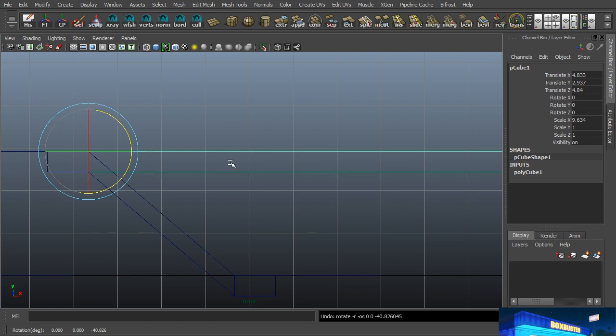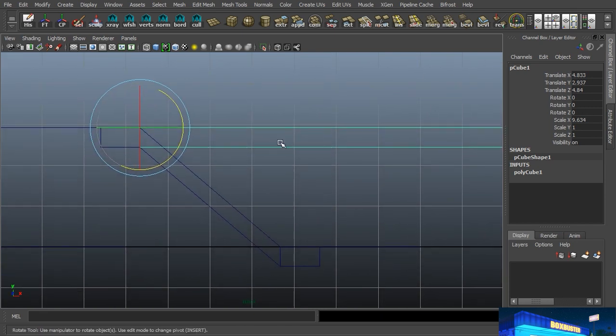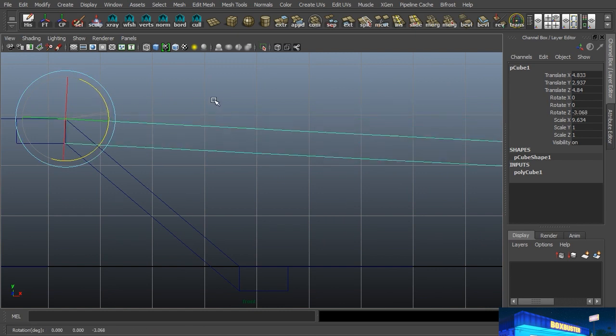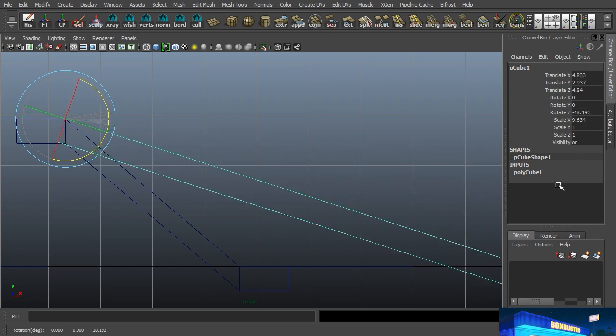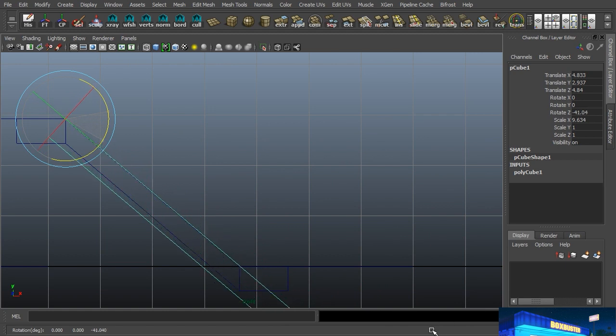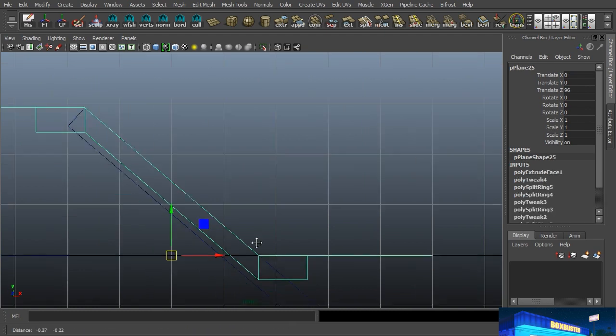So here's a little trick that works out really quite nicely. Rather than grabbing the handle and moving right here, I'm going to grab this handle and I'm going to pull my cursor way over to here. And then when I rotate down, I'm moving a greater distance, so it enables me to be a little bit more accurate as I'm doing this. All right, that looks good.